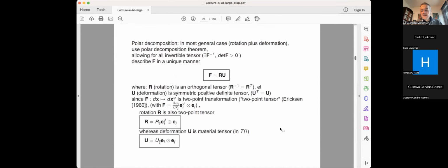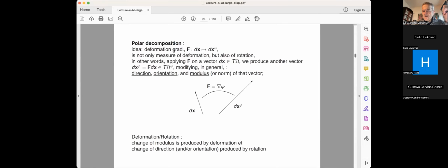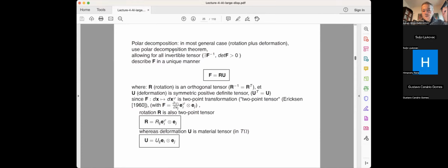So basically, if I now want to take a more general case, where there's deformation as opposed to not having deformation, that means I need polar decomposition. I can assume that my deformation gradient could be written as the product between a rotation and what we call the stretch tensor, and in particular we call this the right stretch tensor because it's on the right-hand side of the polar decomposition, which I denote as U. So U is a symmetric positive definite tensor. Symmetric means U transpose equals U.